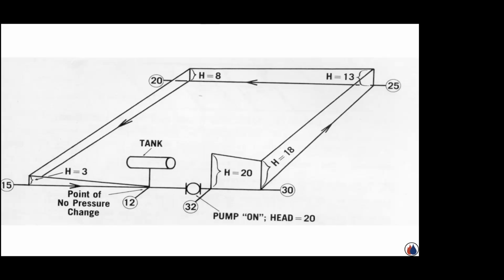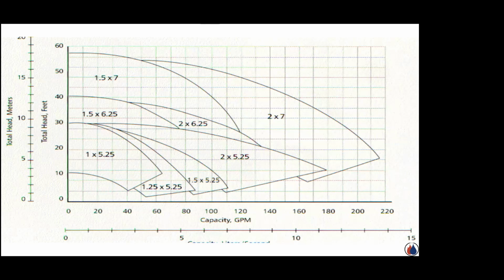Looking at pump curves real quickly, this is just a quick example, but pump curves basically are almost like either blueprints or the DNA of what a particular pump can do. This is just a selection of some Series 60 B&G pumps, different model numbers, and each model number represents various capacities. When you look at a pump curve, down here on the horizontal you're looking at GPM, and on the vertical left-hand side, it's in feet of head, total feet. What kind of frictional resistance can this pump develop to overcome and move a certain GPM that I need down here?